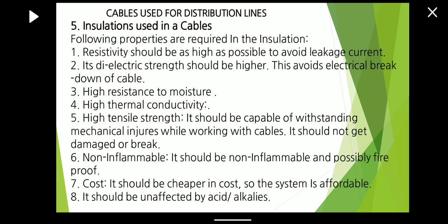To protect the cable from this happening, the insulation is covered with a lead sheath. Then high thermal conductivity, so that it passes out the heat to the next layer, that is the sheath.